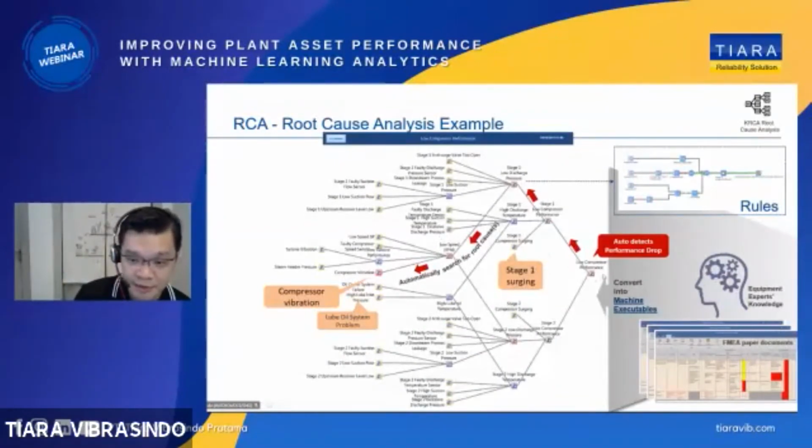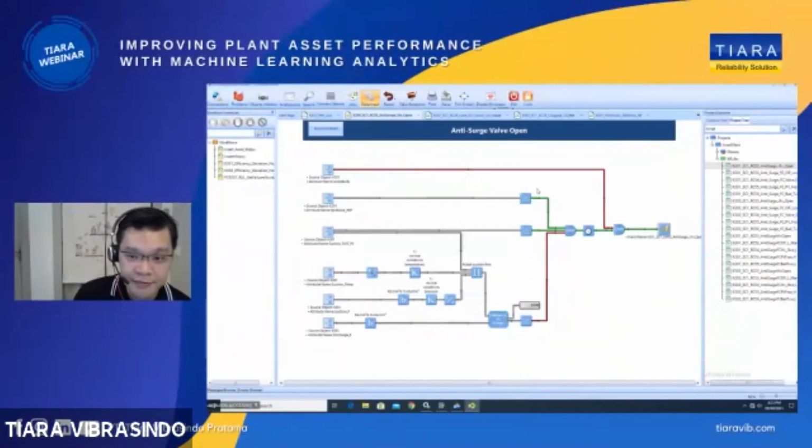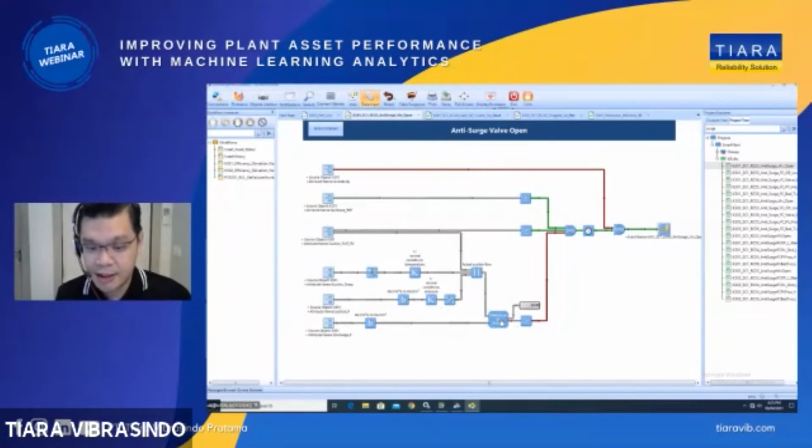Different models are created for different purposes. Just now I created a performance model. I can also create an anti-surge valve model. Just now, as you saw in this machine, the anti-surge valve has a model inside also. This is my distance-to-surge model. Where does this model come from? This model comes from the OEM surge diagram. The software has a way of converting the PDF readings into models.